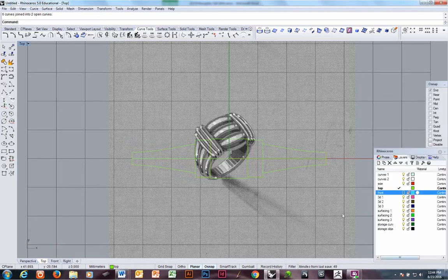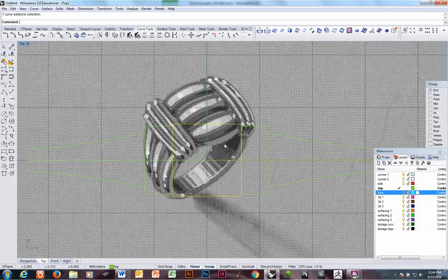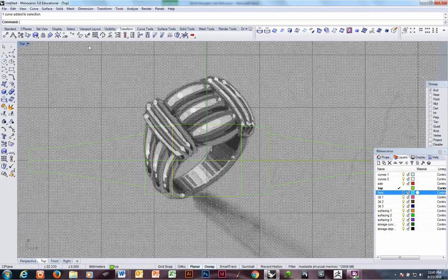That'll help. Okay. All right, so I have drawn those elements. Now I need to draw the remainder of my top view. Okay, I'm going to explode this. I'm going to divide this curve by 3. Transform tab, control points, divide curve by number of segments, which is right click. Number is 3. Let's actually make it 6, because we may want to be able to see the midpoints on these flutes.